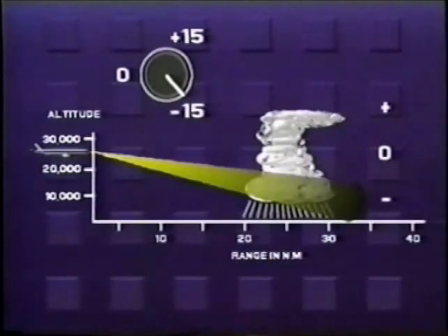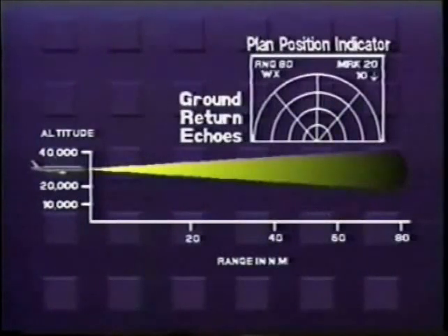In order to produce an accurate radar return from a rainstorm, the beam of the radar needs to be directed toward the lower 18,000 feet of the storm. Through tilt management, this goal can be achieved. Let's say the radar is being used on the 80 nautical mile range in the weather mode while at an altitude of 30,000 feet AGL. The goal is to keep the display relatively clear of ground returns while making certain that no weather cells go undetected in or near the aircraft's flight path.